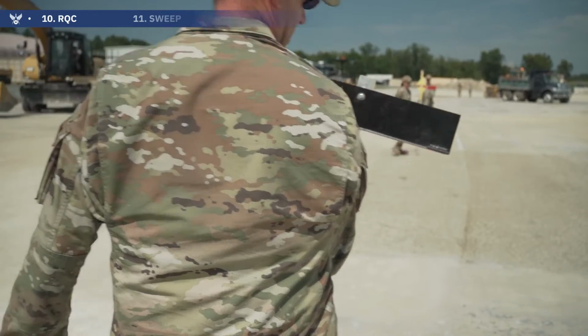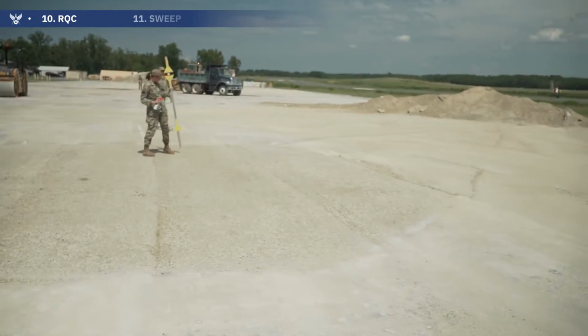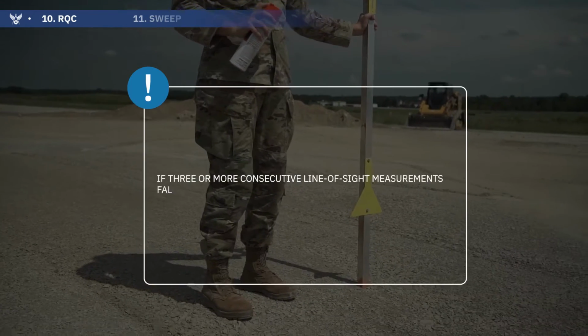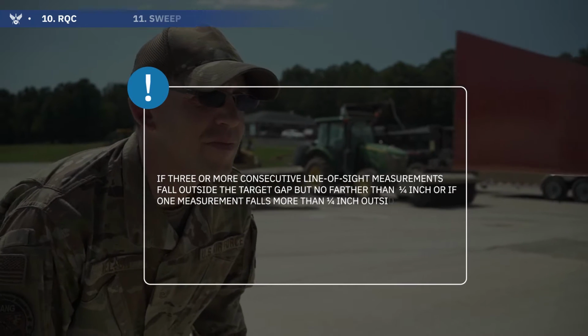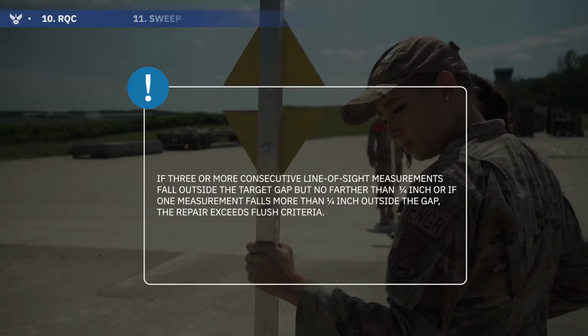Measure across the repair in 2 to 3 foot increments along at least 5 parallel lines. Note, if 3 or more consecutive line of sight measurements fall outside the target gap, but no farther than 1/4 inch, or if one measurement falls more than 1/4 inch outside the gap, the repair exceeds flush criteria.